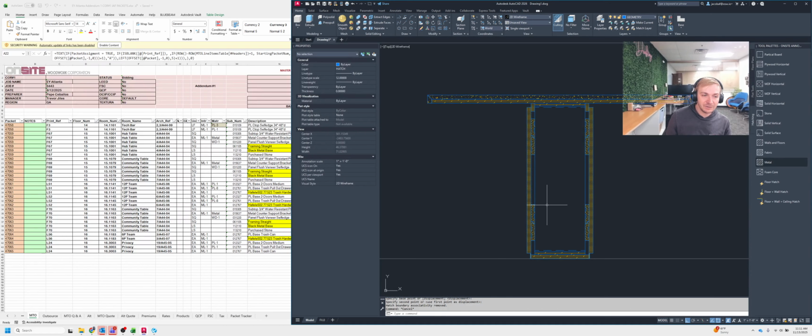We're going to talk about outlets, brackets, and then we need to also incorporate a wire chase into this die wall so the electrician has a place to run wires through the die wall. Let's start with the bracket first because the bracket is by far the easiest of these three things that we have here. So we're going to go to on-site hardware in our tool palettes.